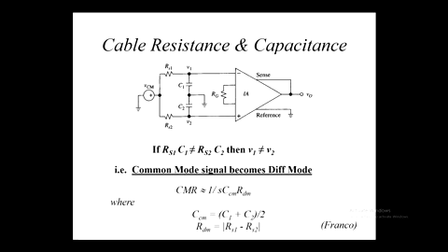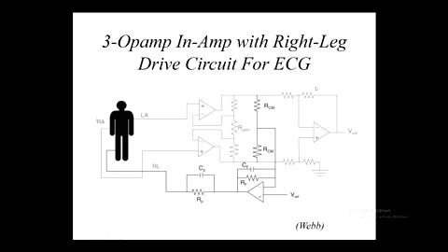So suddenly, common mode signal has become differential. It's different at both points. Therefore, our snazzy instrumentation amplifier will amplify that as if it's a differential signal. Common mode gone differential, gone feral. So that's something to watch out for.